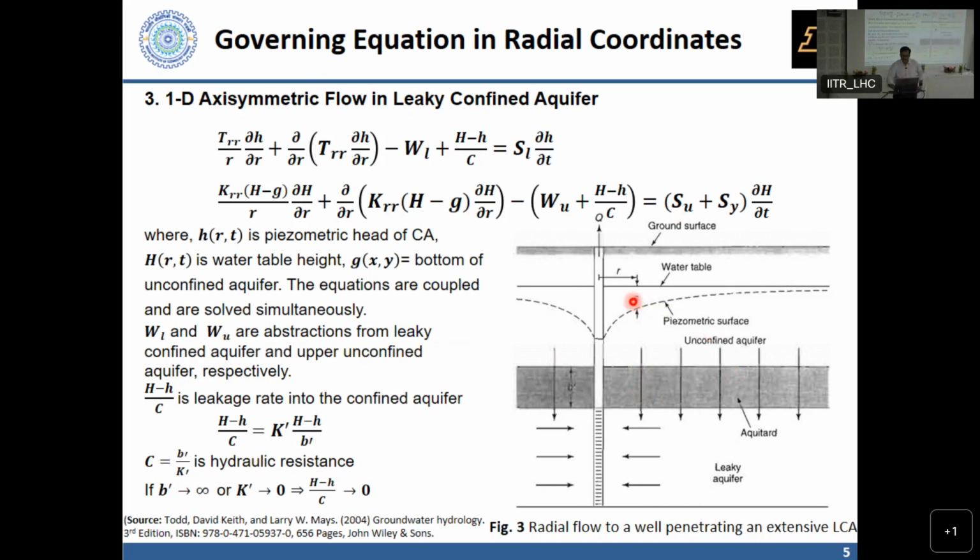Okay, and we assume, let's say, that therefore there is no appreciable movement of water in the unconfined aquifer, then we don't actually need this entire equation. We are basically saying capital H remains a constant, and that simply governs leakage into the main aquifer. We don't need a separate equation to describe what's happening on the other side of the aquitard. So we make that simplification sometimes too.